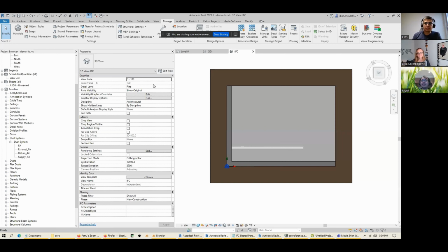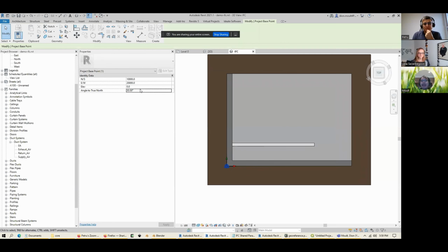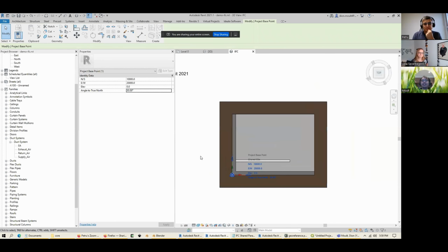And I guess all architects and all the people doing vertical construction need to be aware that when you ring up your surveyor, you say, hey, Mr. Surveyor, what's the coordinate reference system? Tell me the EPSG code. Also tell me grid north. That's all you've got to mention, and make sure you get it down in writing. The last thing you want to be doing as an architect is writing down, as I just did, these numbers manually. You should be getting all this from your surveyor.